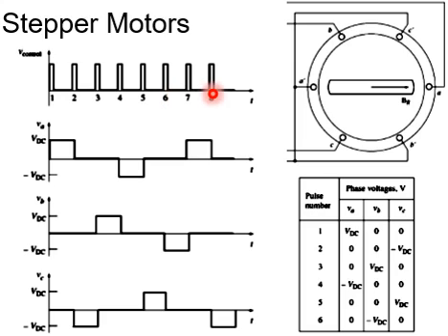Let's suppose we want to rotate our rotor for one step of 30 degrees, then it will be rotated for 30 degrees, then again for 30 degrees, then again for 30 degrees at each step. So 8 steps are shown over here for different time intervals,